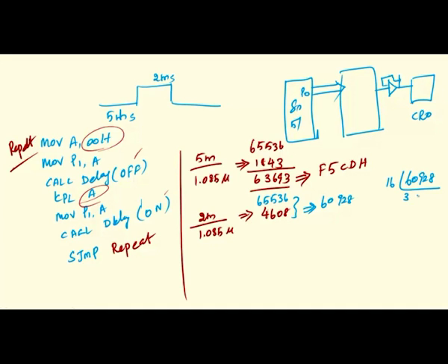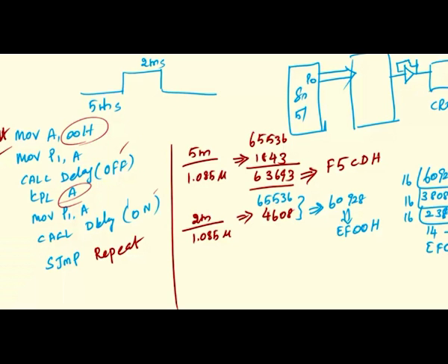So, after that you get a remainder 0, then 808, the difference is 0, again you divide by 16, then you get 238, then 0, then again you divide by 16, now you will get 14 and the remainder is 15. Okay. So, by this you have to write it as EF00H. So, its corresponding equivalent is EF00H. Okay. You take the Timer 0 register for initializing the counter value in case of a 16 bit delay.